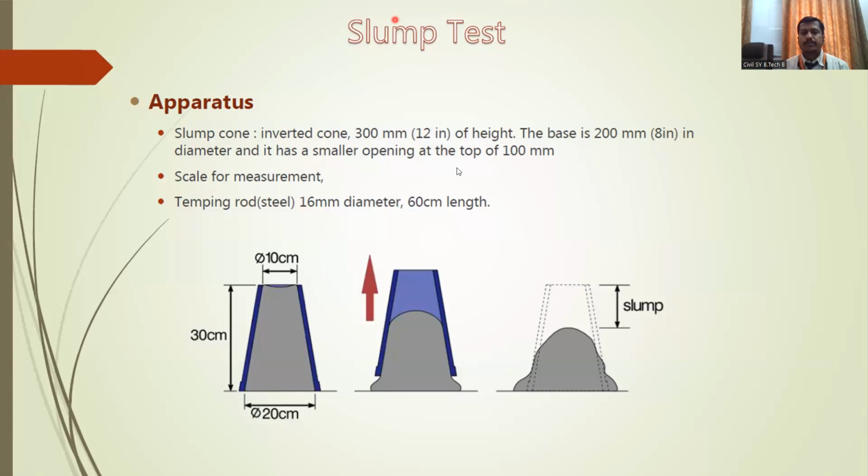So as I told you, if you are just going to lift this cone, it may happen that concrete will gain the shape as like your cone, or it may gain the shape like this. It totally depends on the quantity of water that you have used in making that particular concrete mix. Okay.